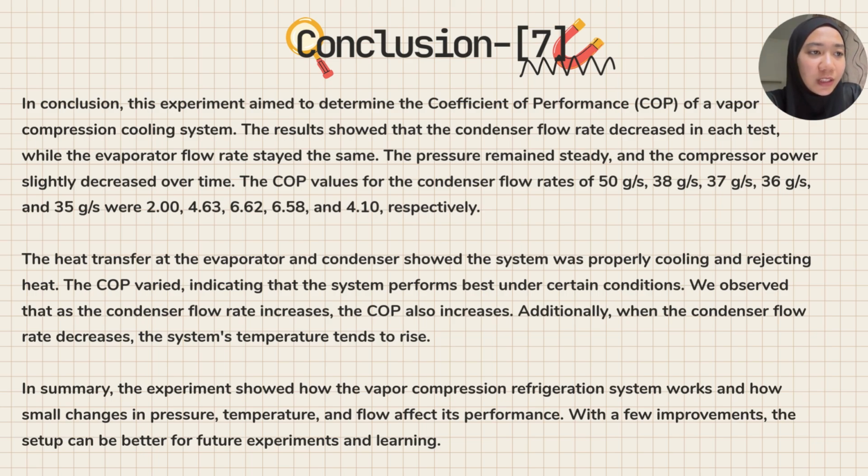The heat transfer at the evaporator and condenser showed the system was properly cooling and rejecting heat. The COP varied, indicating that the system performed best under certain conditions. We observed that as the condenser flow rate increases, the COP also increases. Additionally, when the condenser flow rate decreases, the system's temperature tends to rise.